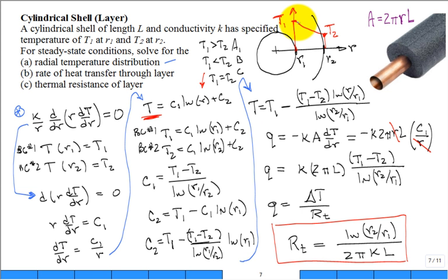Okay. You have these two boundary conditions. You solve for C1, you solve for C2, you stick it back into your general formula, and now I would box that and say that's our radial temperature distribution right here. It still has that log of R, but it also has the log of R1 and the log of R2 tucked in there, and that's about as compact a form as we can get.